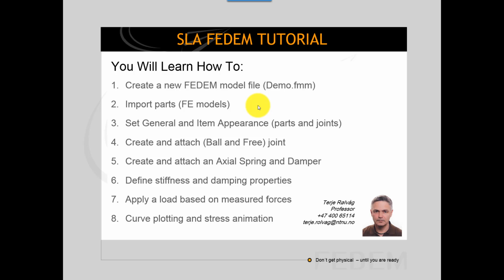Finally, I will apply a load which is based on measured forces from practical or physical tests, field tests. And finally, I will show you some basic post-processing features in FEDEM. I will plot curves, and based on those curves, I will identify the most severe loads. And then I will do a stress analysis and create a stress animation.